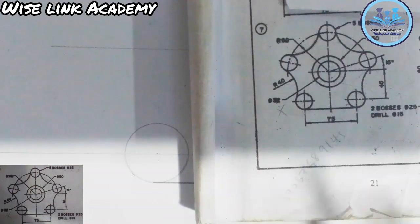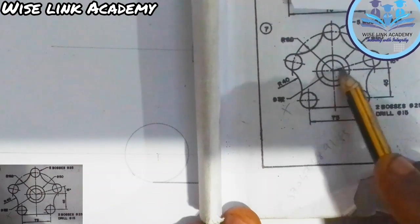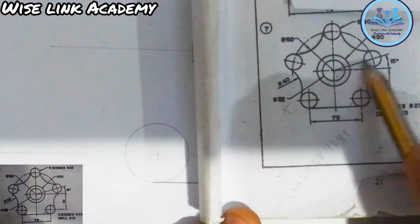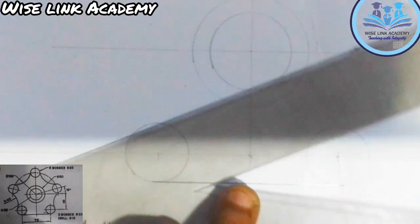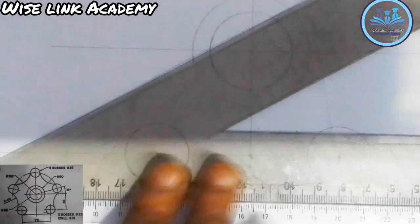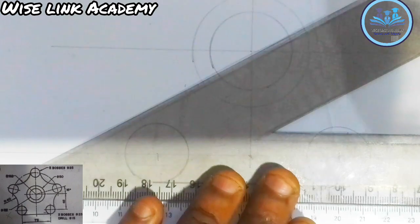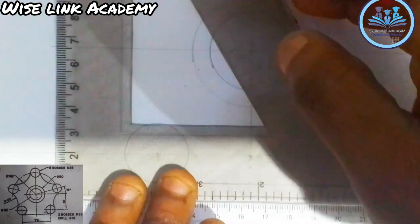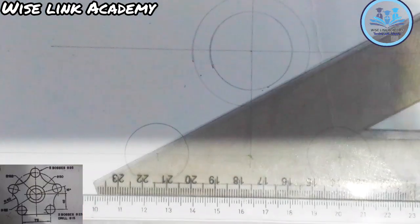The next thing to do is, what do you observe? From this center point, they said there's an angle of 15 degrees. So I can just take my set square. This is my set square this way. If I place my set square this way, it is 30. Am I right? If I place it this way, like this, it is 60. Am I right? 60. So I want to draw 30. From that 30, I will now bring out 15.